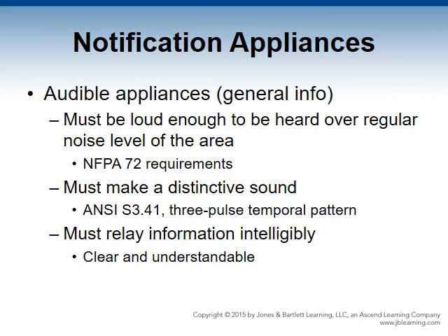Although model code requires the temporal pattern for new construction, it can be hard to ensure that the entire building system is upgraded. In buildings that have undergone partial and entire floor renovations, there may be different audible appliances that produce different sounds. Many jurisdictions require a floor to have the same type of device throughout to avoid confusion.